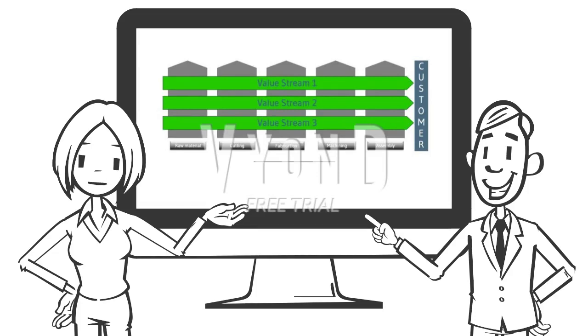Suffering from massive inventory between processes and several accidents with the forklift, one plant manager set no forklift on the shop floor as the goal for their new plant layout. The lean layout reduced material handling dramatically, forklifts were not required anymore, batch sizes were reduced. This led to less work in process inventory and shorter lead times.